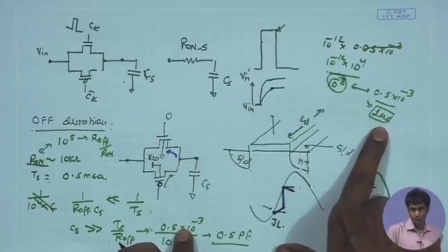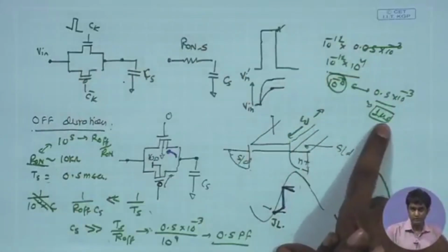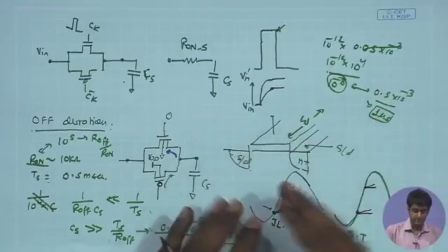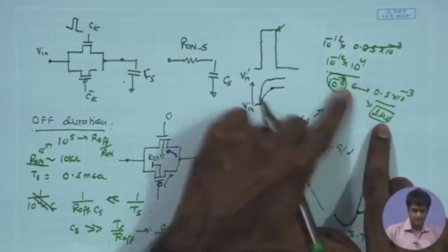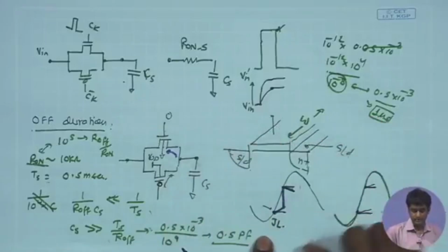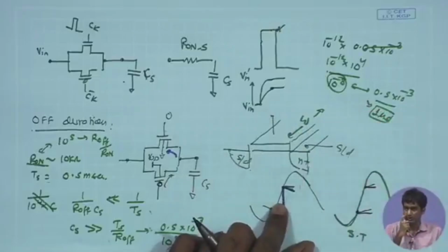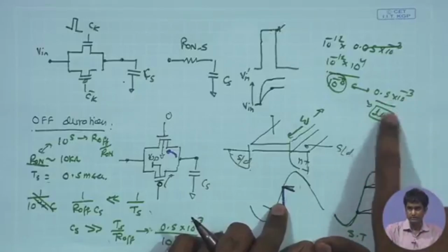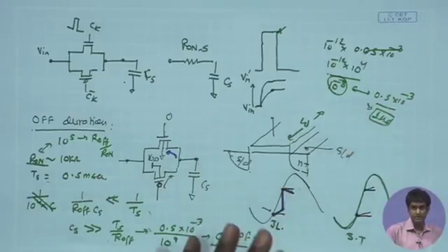Why are we not going for lower than 1 microsecond? That has something to do with the generation of this 1 microsecond pulse. We will see that when we go for the digital control, how these control signals for sampling, switching, etc., will be generated. Ideally speaking, we can go down further, into the sub-microsecond regime, but for the time being let us choose 1 microsecond because it is significantly small compared to our overall sampling duration of 0.5 millisecond. If this is close to 1 microsecond, it is hardly significant compared to the entire sampling period. So, let us stop here.